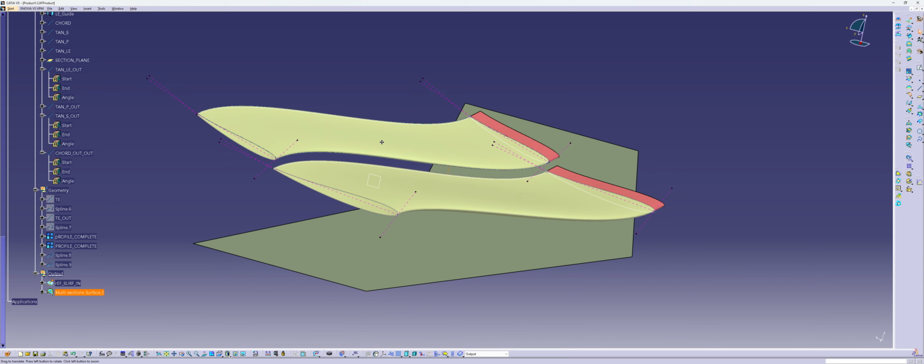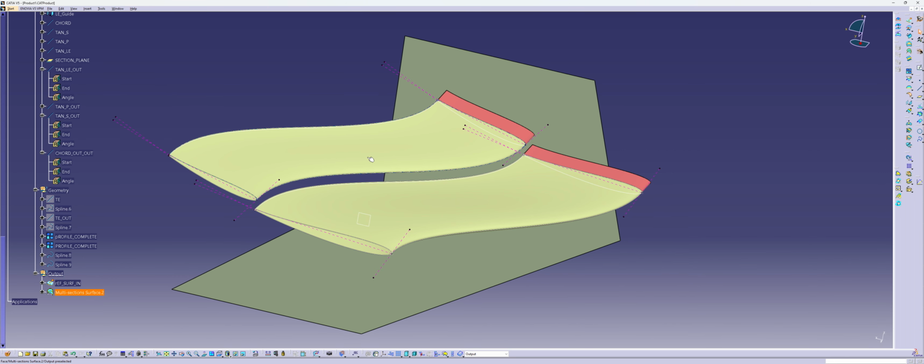So you can test it in CFD, see the results, see that you have separation somewhere, lower the angle, and test again and again. Don't need to build new wings every other week. You can just adjust the one that exists already.